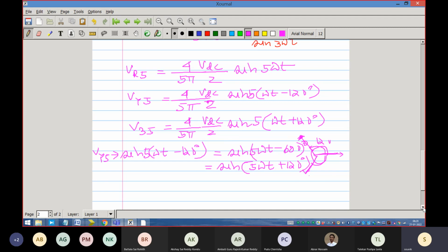That was the switching strategy, where we have produced discontinuous square waveforms. Now, after Fourier analysis, what we are seeing is that the fundamental component is maintaining that kind of phase shift, meaning that the fundamental component of the Y phase is lagging the R phase, and the fundamental component of B phase is lagging the Y phase. There is no doubt about it.